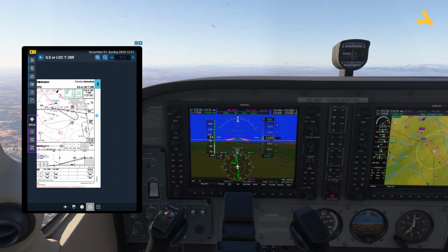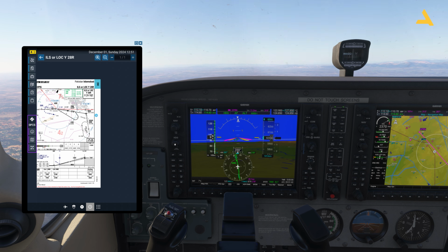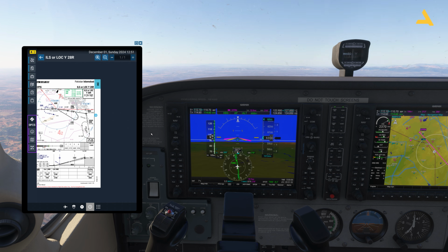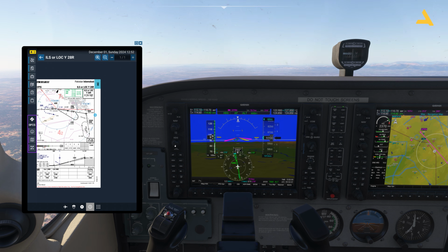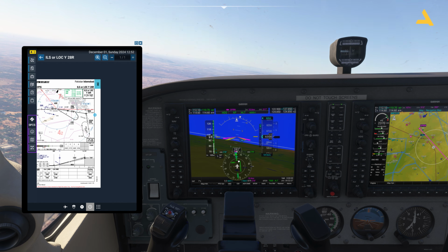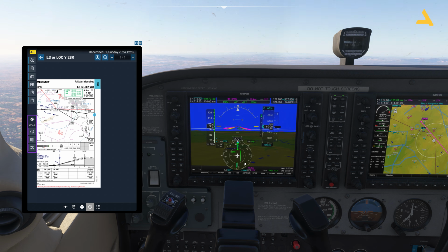110.7. Now IB. Okay, you can see this identifier is coming. This happens. Okay, so it means now you're tracking the ILS. So let's adjust the course. Now at some point I will be here. So at this point I can also start tracking the ILS, but now you can see this ILS information is not coming.